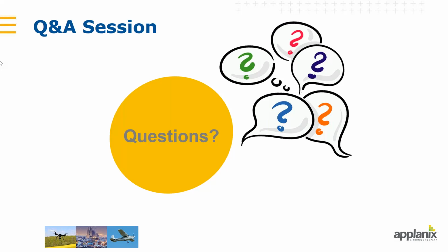And then there is another question: how to add a mapping frame if a specific one that I need does not exist? Yeah, that's pretty open in POSPac. Right now, you can easily add a mapping frame in POSPac. You would need to check first that the projection is supported. We support a wide range of various projections. But if the projection is supported in POSPac, you can add any mapping frame or any grid to POSPac as long as you have the parameters.